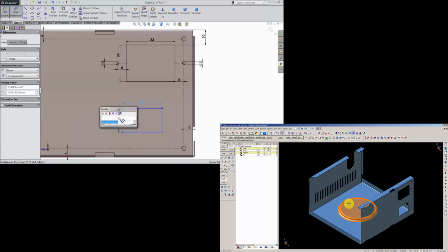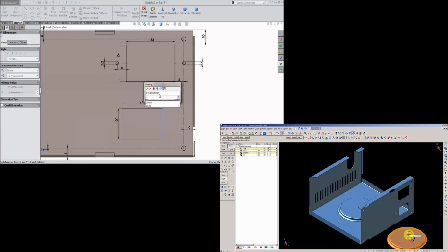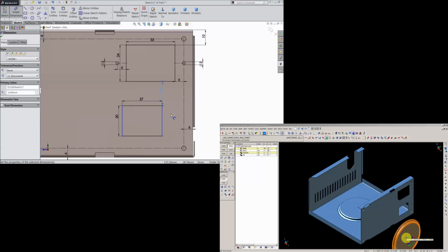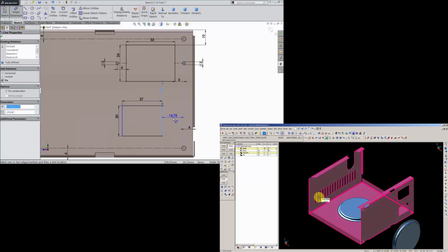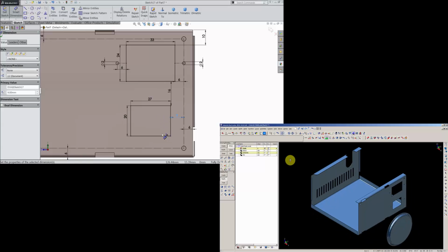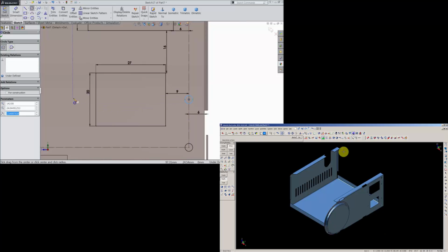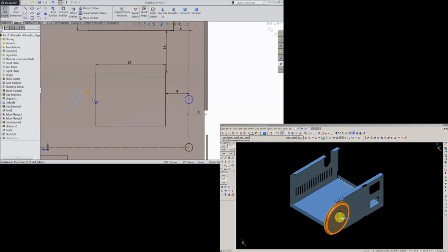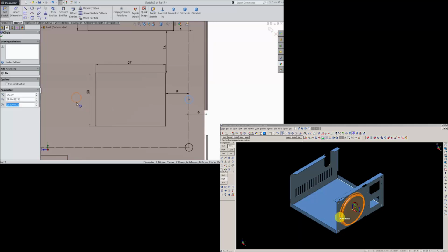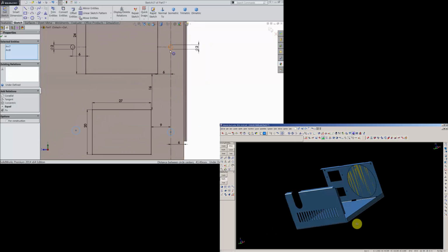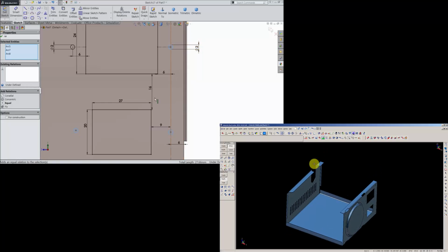.27 mm and the height 20 mm and this gap 16 mm and the distance from this line make 9 mm. Now again define 2 more circles. Select these 2 circles and select one previous circle and make relation equal. Now this equal.